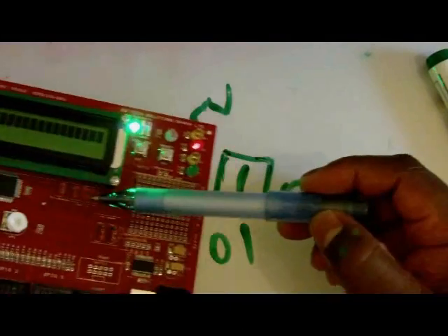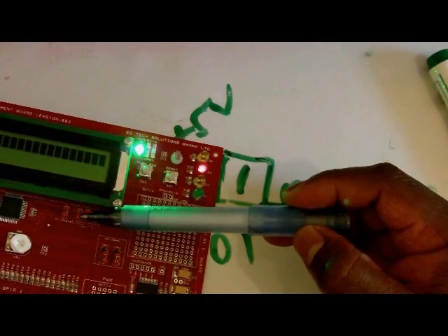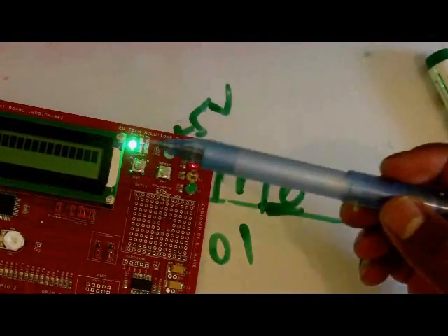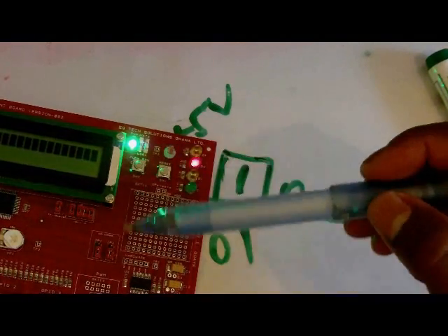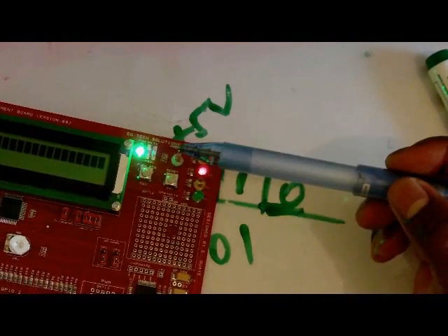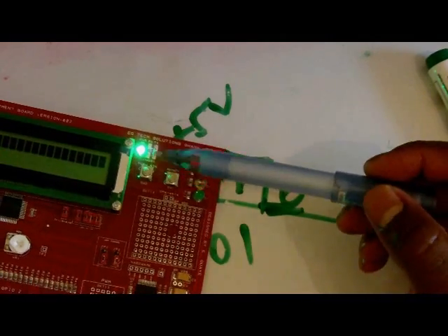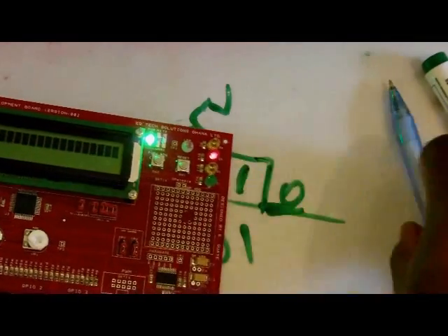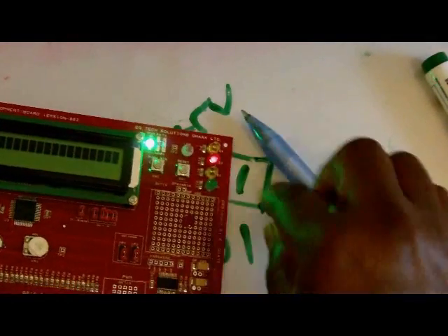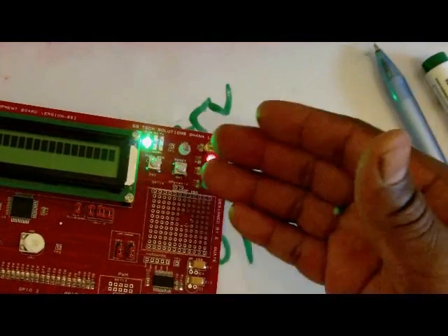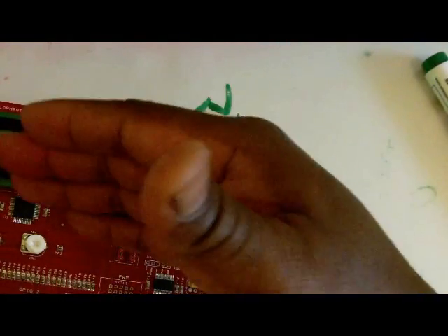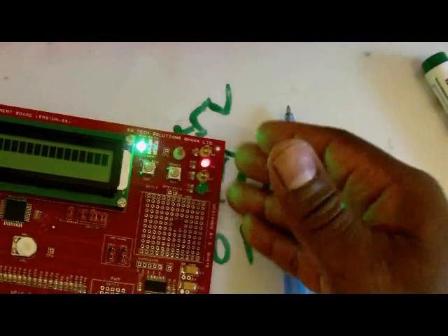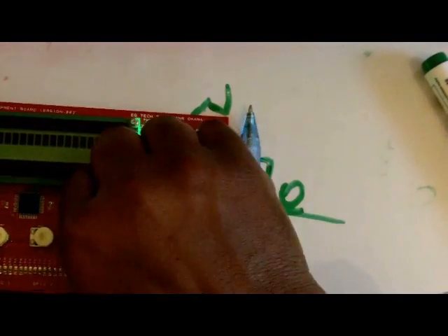But all the same, I put these jumpers here so that if you require in future, for a project, maybe you want to communicate with a GPS and at the same time send information through GSM or maybe ZigBee or XBee, then what you have to do is pull the jumpers off, and this light is going to go off. That means you are freeing those pins, or the control lines to these LEDs. So you pull all of these off.